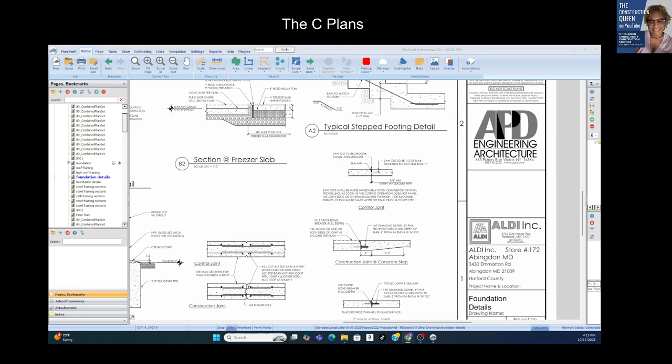All right, and we did go over reinforcement, how it's represented, how you look at it, how you count it up, and how it is represented, right? So you take that section view of the rebar at that section view, but before you even went to the section view, you determine how many linear feet was there, right? And so now if I have four number fives, and I knew I had 100 feet, well, that's 400.